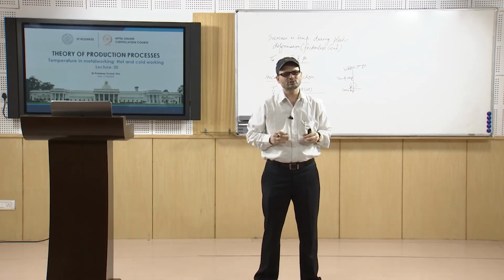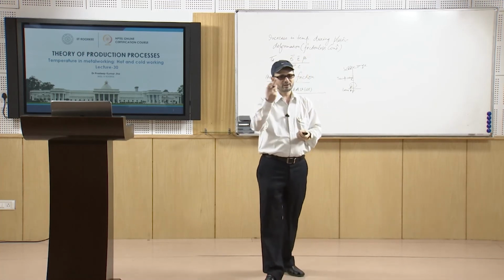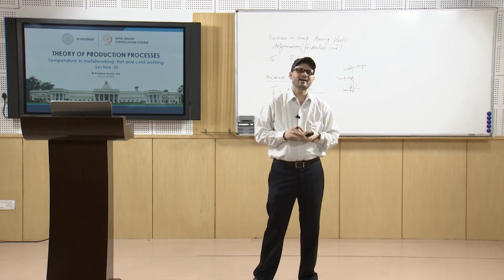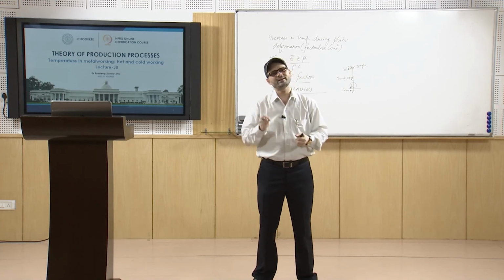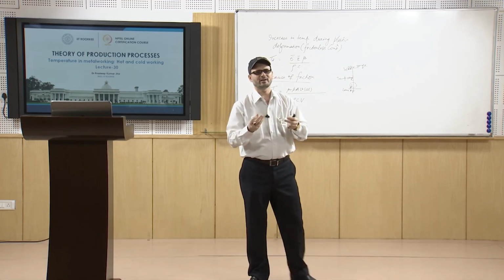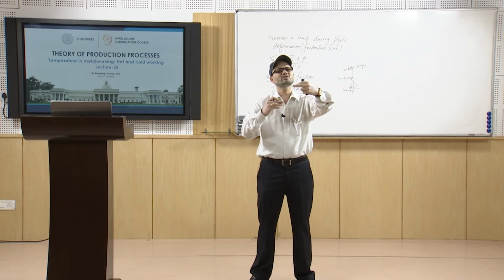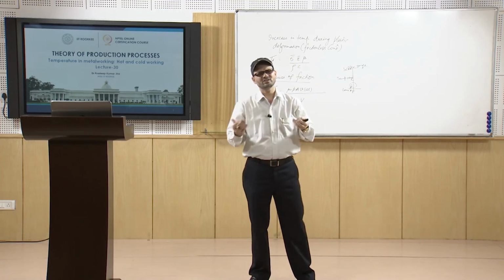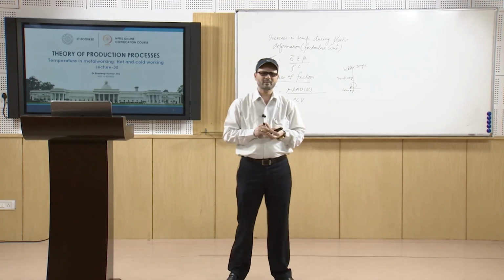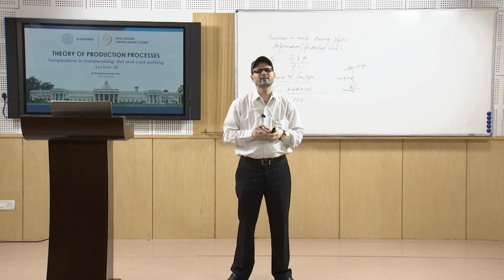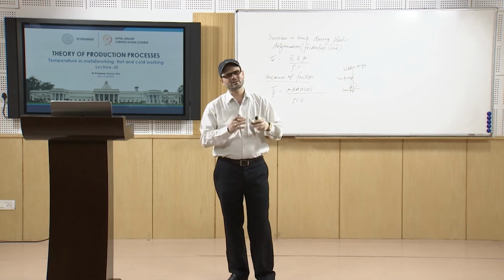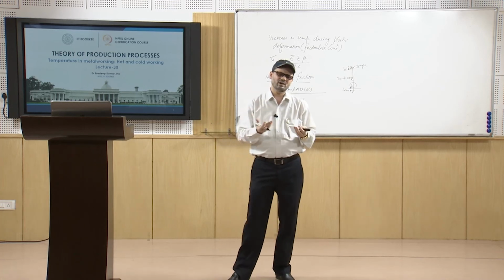Similarly, in the case of wire drawing, you can control the temper. Based on this cold work and anneal cycle, you can have different kinds of hardness or properties of the wire itself, like spring temper, quarter hard, half hard and so on. This is all based on this cold work anneal cycle. So, this is how we see how important temperature is in working, and we will study the different processes, based on temperature itself, as cold working and hot working.